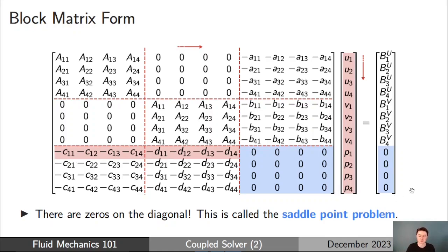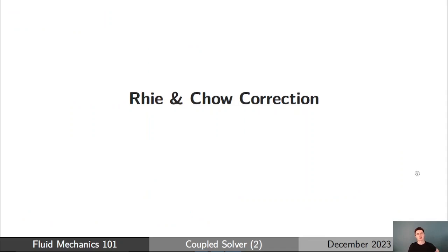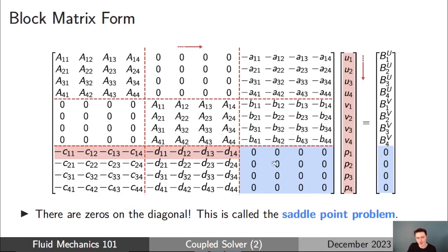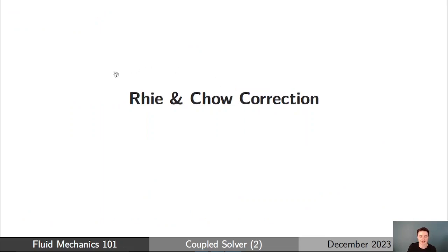And that's what I want to focus on in this talk. So we can't use the continuity equation directly. What do we need to do to allow us to formulate this coupled matrix equation correctly? Clearly, we need some method of getting the pressures involved in that matrix equation for cell 1, and we need some way of getting a source vector there. And the key is to use the Rhie and Chow correction.